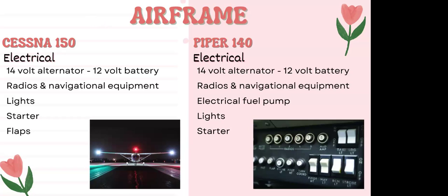And I'm sure that at some point, for those of you flying the 150 or even the 140, your CFIs will do landings with you that are no flap. And what that means is being able to manage your energy and come in to land when you don't have access to, basically, your air brakes is what flaps are. So if we ever had a problem in the 150, you'd be well equipped to say, hey, I've practiced this before. I know how to come in and manage my energy and land without flaps. So that's just one of those quirks with the 150.